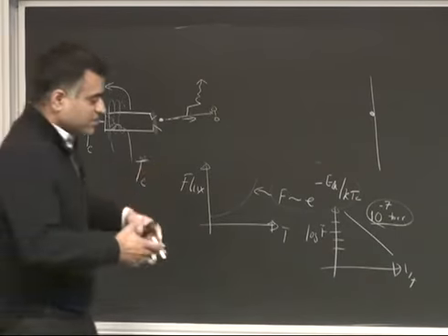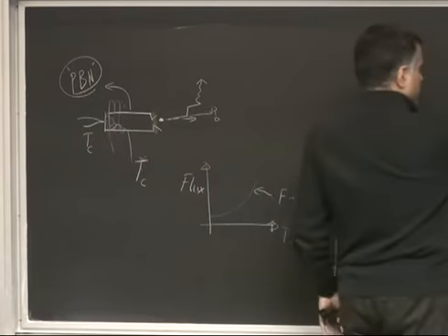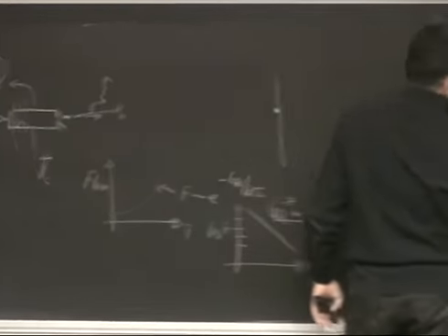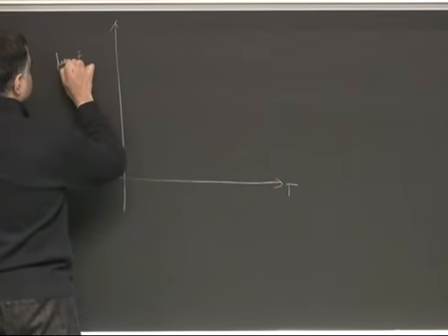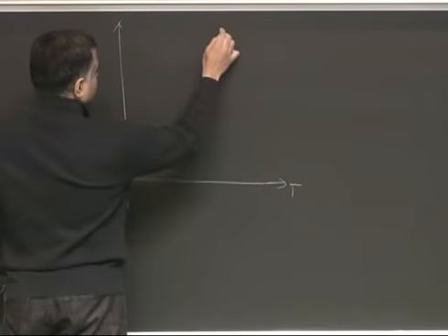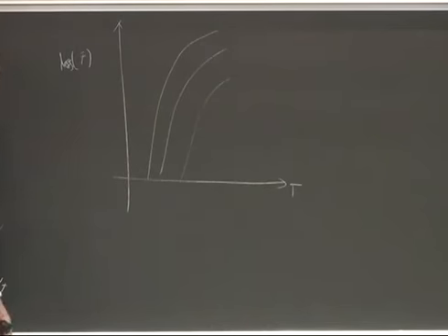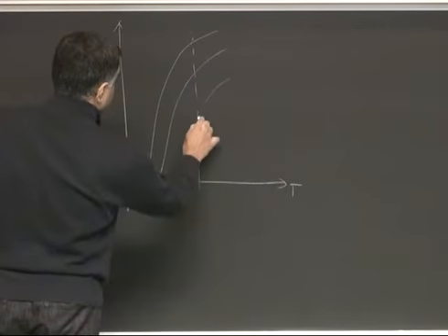Right? You heat it up, but then not all. So what you'll see if you look at effusion cells is what will be labeled typically: the temperature and the flux. Generally, it's plotted as a log of the flux. And I think in material science courses you might have seen these. They are called the vapor pressure curves for various elements: gallium, aluminum, indium. All kinds of elements have different vapor pressure curves, right? So that really defines what sort of temperatures you want to operate at.